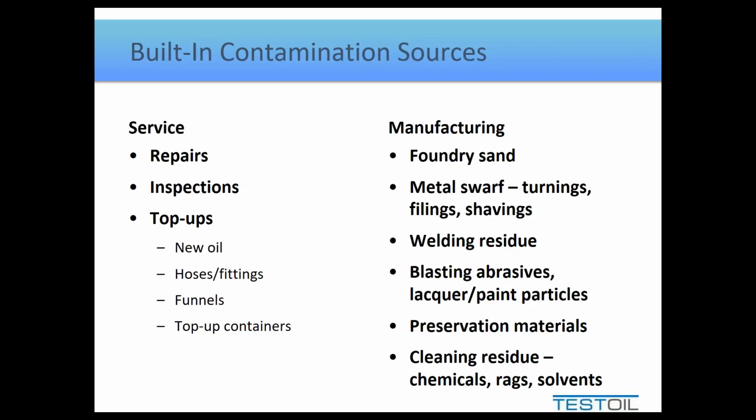And what we in the end can usually attribute it to is a reaction to the original preservation oil that wasn't flushed out. They simply topped it up with some residual preservation fluid in there. There's often some incompatibilities between that preservation fluid and fully formulated products.